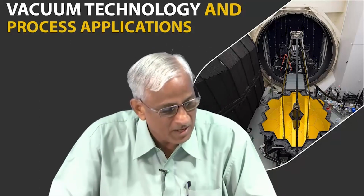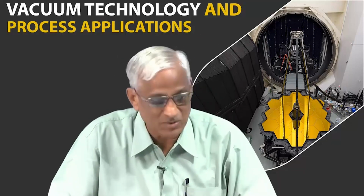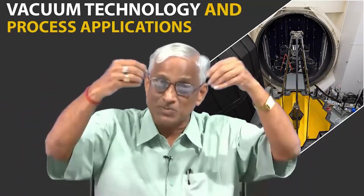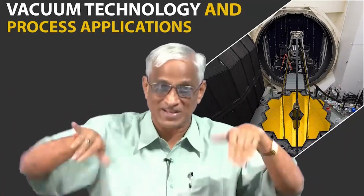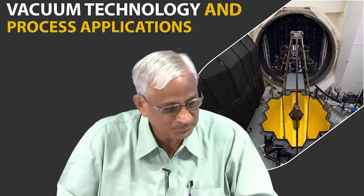Okay. And we also have to increase the temperature of the body by baking it. So, baking is a very important operation. While baking, the natural oxide layer can also form with the small amount of oxygen which is available, which is absorbed. That way oxygen is removed in the process of baking on the inner side. We can bake from the outside by heating, but since stainless steel is a thermally good conductor, even with a small thickness, it will be uniformly baked. The inner surface is hot. In those hot conditions, oxygen and whatever layer is there gets oxidized. That itself will form a passivation.